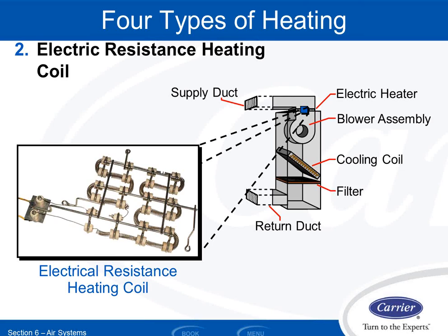And if you're in cold climates, and cold climates pretty much means Atlanta and northward, you need to have a freeze stat in your air handler that detects if the air coming into the chilled water coil ever gets below about 37 degrees. I go into oh crap mode and I shut off the blower, I close all my outside air intake dampers, I open up all my chilled water and hot water valves to move as much water as possible if that were to happen. But on a DX refrigerant-based system, there is no risk of the refrigerant freezing and any damage being caused.